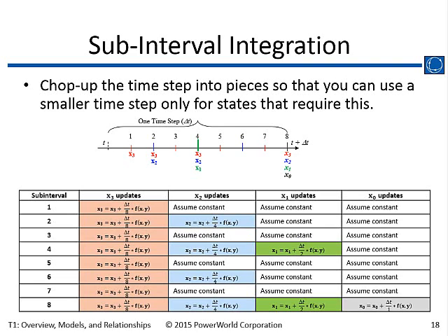You can't tell for sure because they show the same results. There is one trick: if you do a run, then halve the time step and get the same response, it was probably an actual instability and not a numerical one. You can easily do this in PowerWorld: rather than a quarter cycle, run 1/8 of a cycle. It'll take probably twice as long, but if that instability goes away, then it's numerical.